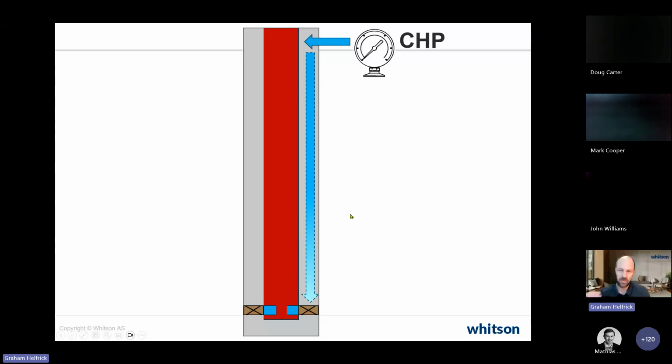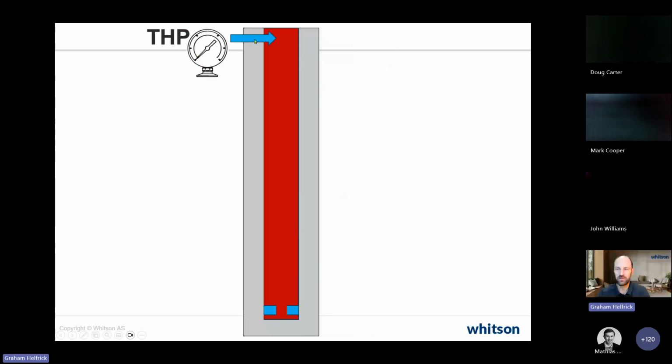This has been a struggle for everyone in the past, but we've finally just recently included chokes. So what we can do now is use the tubing head pressure, and we calculate from the surface down to the outlet of the choke, then do a complex pressure calculation across the choke, and then another pressure calculation from the choke inlet down to the perforations.